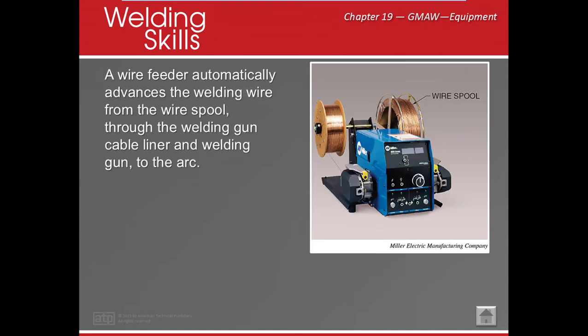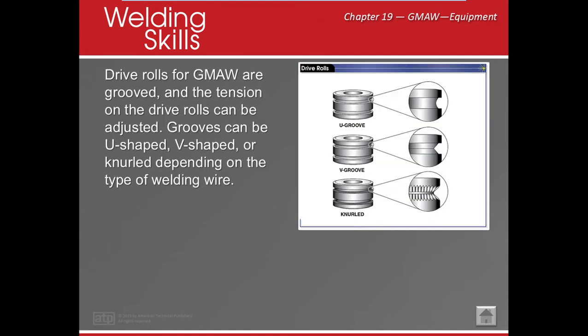All right, onwards. I was saying the wire feeder advances the wire through the cable liner to the gun and then to make an arc. Wire feeders can use all sorts of different types of wires, like flux cored wires too. For the variety of wires and wire sizes, they need drive rollers. These advance the wire in the machine. Drive rolls have to be the same size as the wire you're using, otherwise it'll just slip around. There are also special drive rollers if we're using flux.